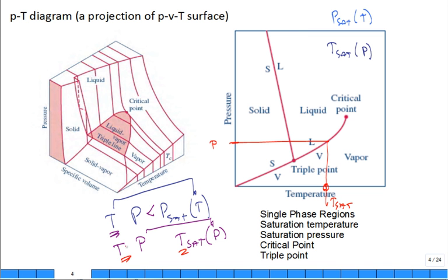If the physical temperature T was greater than, so maybe I got that in the way, put this over here, T is greater than T sat, then it's superheated vapor. Or if T is less than T sat, then it would be something like, well, I should have plotted it along the same line of pressure, shouldn't I? Stay on the same line of pressure going across. If the temperature is less, hey, it's in the liquid.